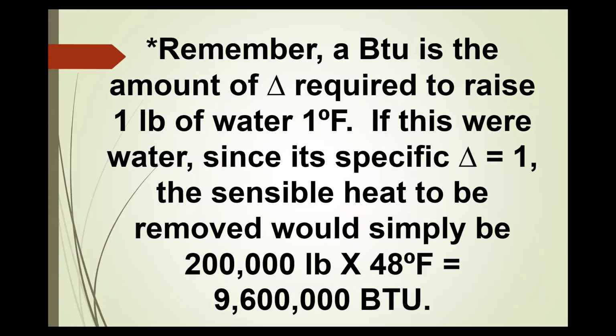Remember, a BTU is the amount of energy required to raise 1 pound of water 1 degree Fahrenheit. If this were water, since its specific heat is 1, the sensible heat to be removed would simply be 200,000 pounds times 48 degrees, which is equal to 9,600,000 BTUs.